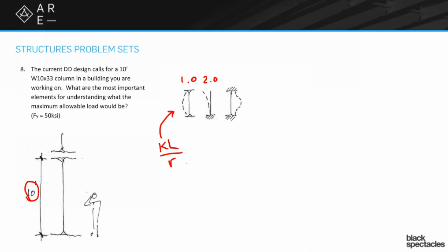On the converse side, let's say instead of being 10 foot tall, it was 1 foot tall, and we put a whole big load on it. Really, you're going to buckle a 1 foot tall steel column? You're never going to buckle that, but if you put enough load on it, it might crush the steel or rip through it. So clearly, there are a bunch of situations where you focus on the material issues, a bunch where you focus on the buckling issues, and some in the middle where you probably have to do calculations for both because it's not clearly one or the other.